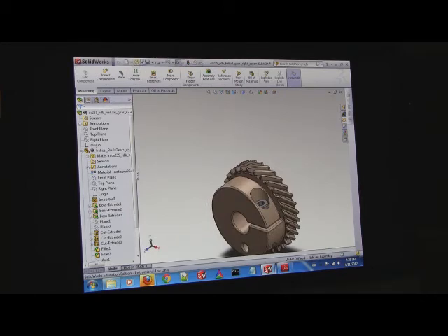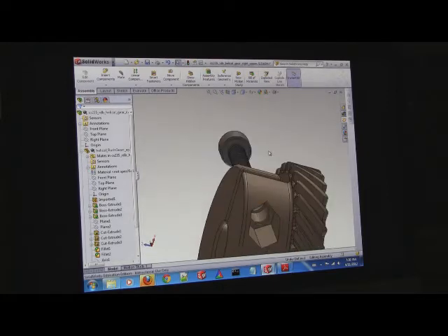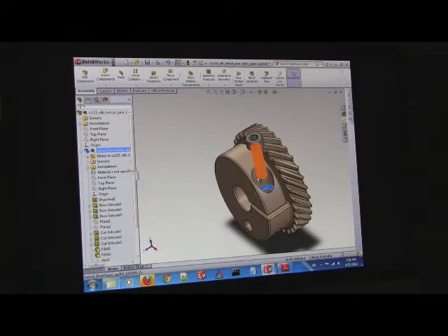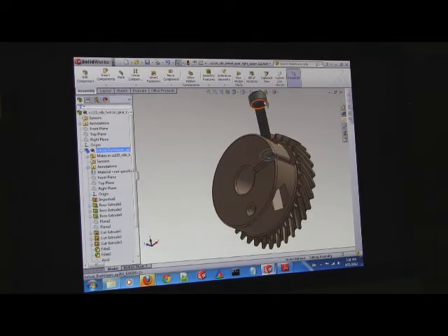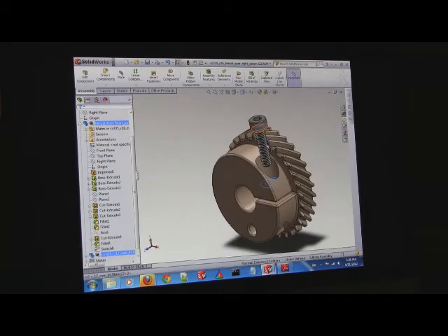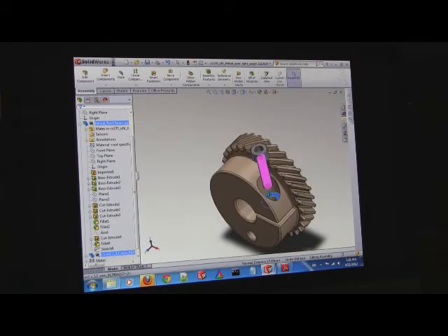So now the screw is properly seated, the bottom of the screw and the bottom of the hole that it's going into. Here, you want to see again? This right here. Select that and the bottom of the screw, and hit Control so that you get both of them. That one and that one. Okay, and then hit Mate.